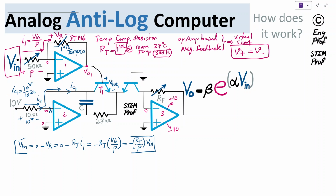That is what I have here, which means 1 milliamp. Okay, so how are we gonna apply that? I can say here, I know VBE1 is the voltage of base emitter or a p-n junction of transistor T1, so I can apply the Shockley junction equation, which says voltage of a p-n junction is just ideality factor eta times Vt, the thermal voltage, which I'm going to just quickly show, and then natural logarithm of, let's say, IC1 divided by the saturation current Is.